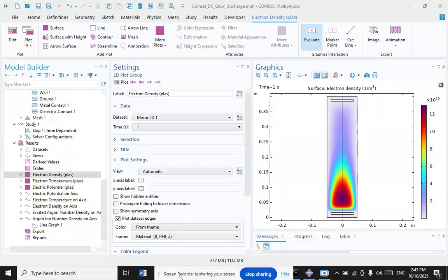And what about applications? Surface treatment is the first application, used to alter wetting properties and clean surfaces, such as thin grids for microscopy, ensuring uniform sample adhesion. The next one is vacuum coating, which serves as a source of high energy ions for sputtering and ion plating processes, which are used to deposit thin films. The next one is analytical techniques. Glow discharge is used in spectrochemical analysis like GD-OES and GDMS for direct elemental analysis of solid samples.